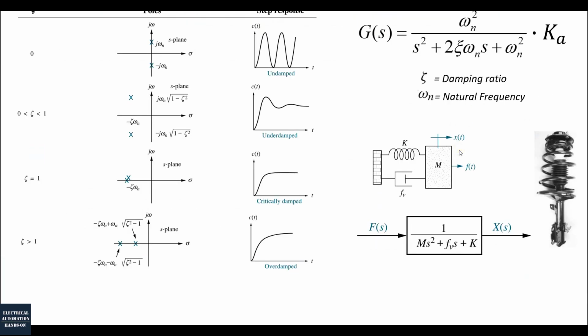Okay? Firstly, we can use Matlab. We can create one second order underdamped transfer function, create a time response, a bump test response, and using the curve, we can determine this second order transfer function.